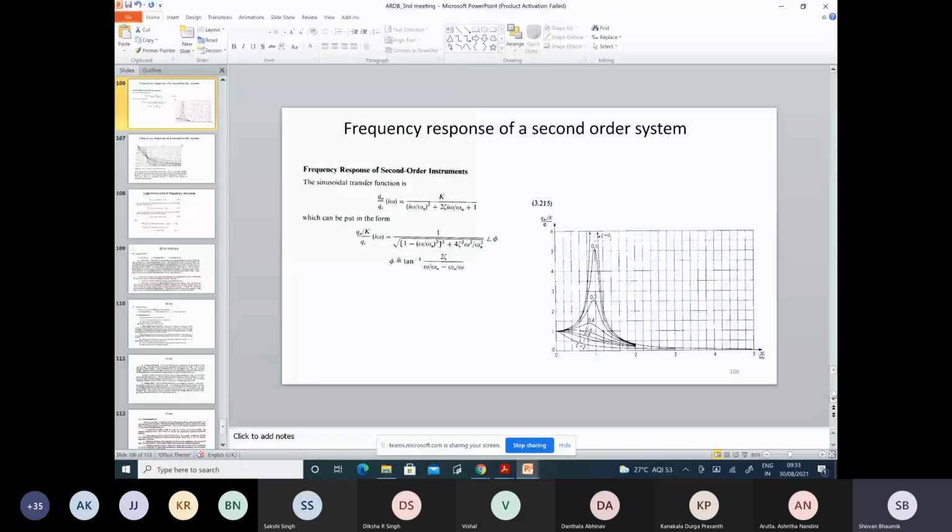Now this is a very tedious and laborious way to plot. Although now you have computers and different apps where you can directly give the transfer function and it will give a direct Bode plot. That is obvious. But still, if you want to draw it by hand, this is a laborious process, and it does not carry much physical significance either. So now let's see, there is another way of thinking, if you can plot it by seeing the transfer function, not by calculating the gain for each frequency. How can you do it?